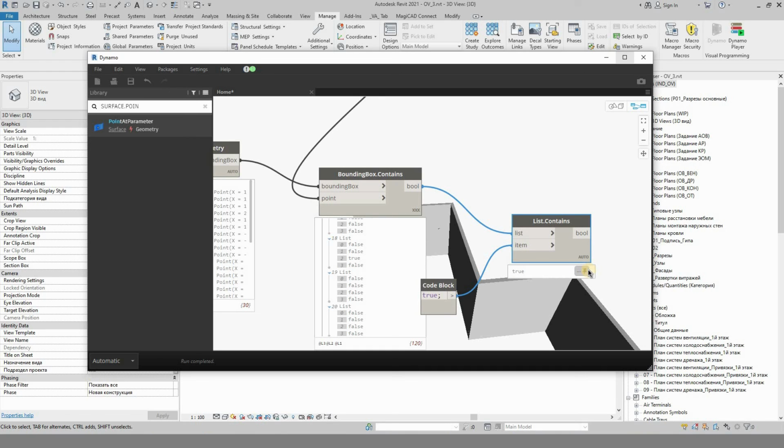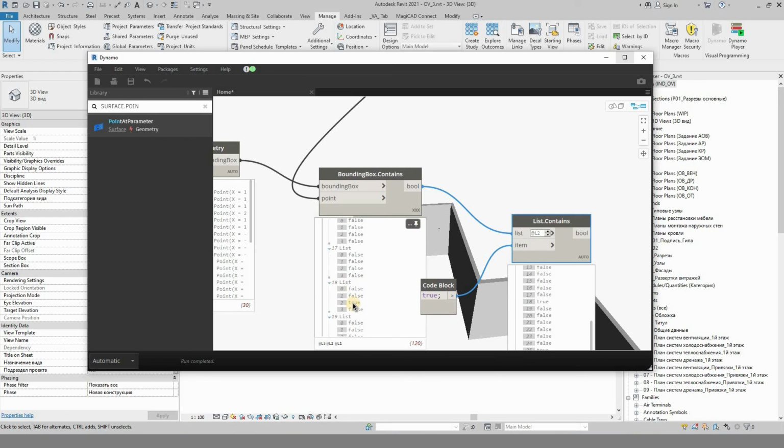True. Okay, what it's doing is actually scanning all of the elements right here, like it's a 1 list, but I wanted to change the level because I want to check on this level right here, not the level 1, not the level 3, but the level 2. So I'm just going to be using levels, level 2, and now we have 30 lists, and it's a good thing to check. So in this index 18, we have a true value, so it returns true. 17, all false, it returns false. So it's working. Let's continue from here.